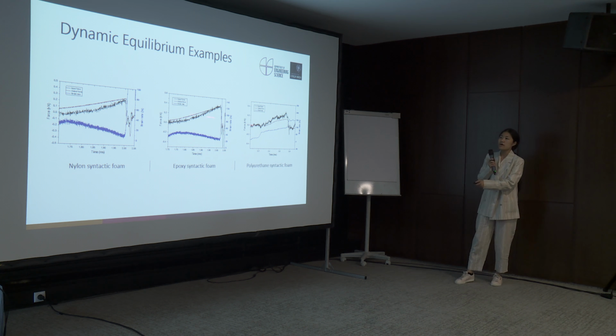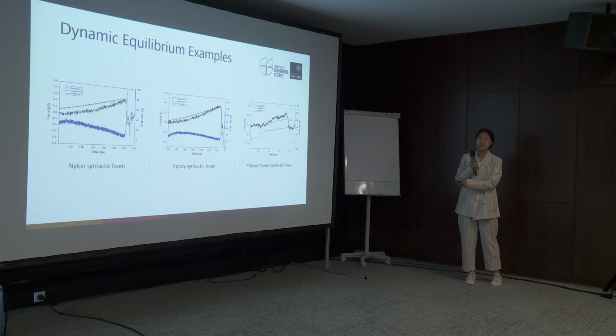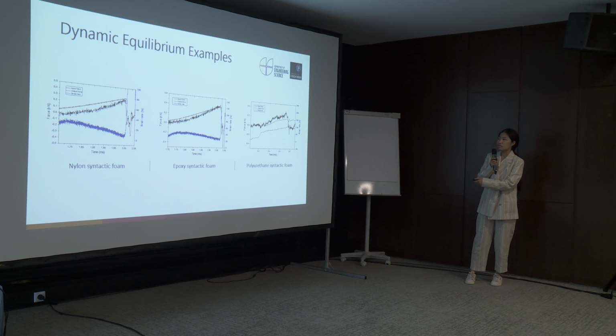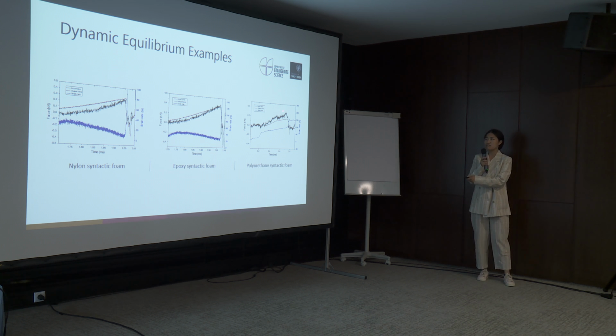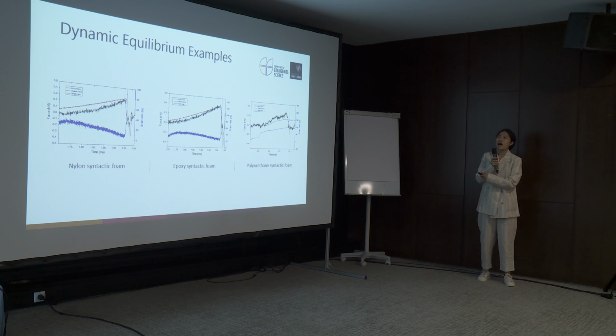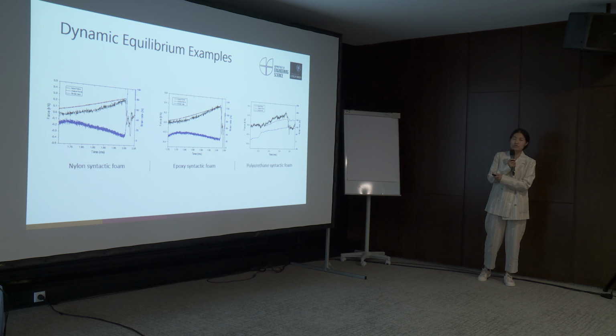These 3 plots show the typical forces measured in the incident bar and the transmission bar under tension loading at a strain rate of 50 per second and at room temperature. It can be found that dynamic equilibrium had been achieved at the initial elastic deformation stage, which validates that our experimental results are valid.